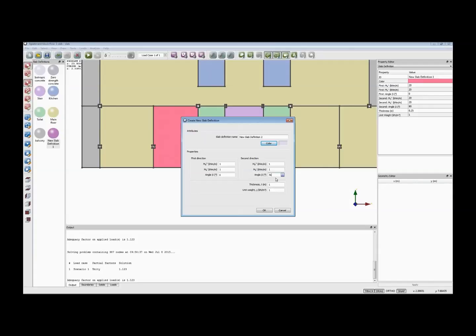But certainly from discussing this with our customers, they feel that the use of a relatively limited amount of load testing plus application of the automated yield line method gives them the assurance that they need to verify that, for example, an existing slab is okay, for example, to house their multi-gym on the 8th floor or whatever it might be.